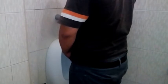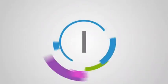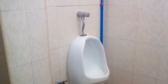If a user stands in front of the urinal for more than 3 seconds, the flushing control device will flush the urinal for 3 seconds. The first flushing. When the user leaves the urinal, it flushes for another 4 seconds, then stops automatically. The second flushing.